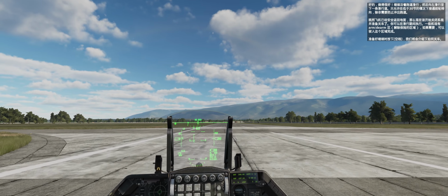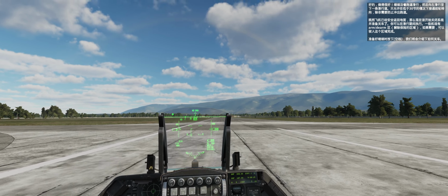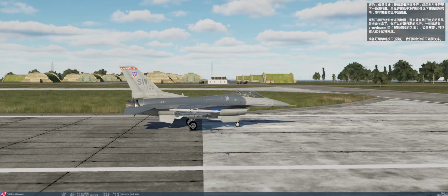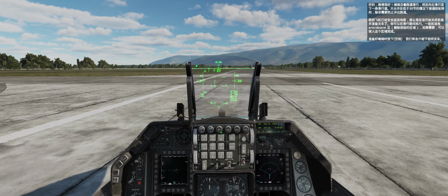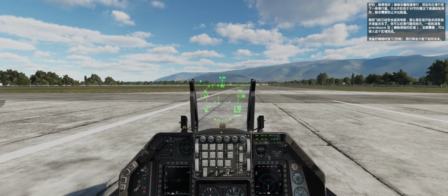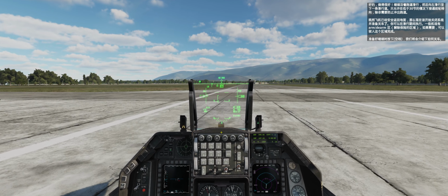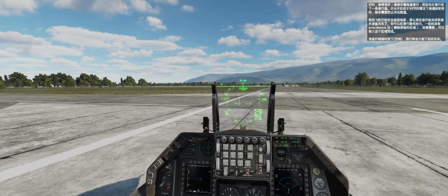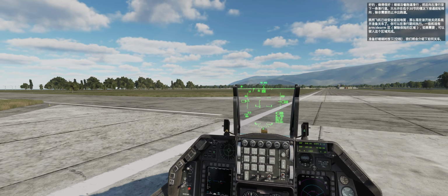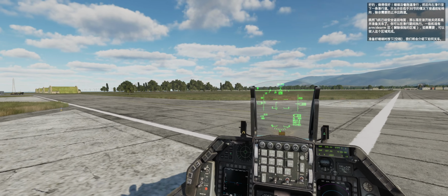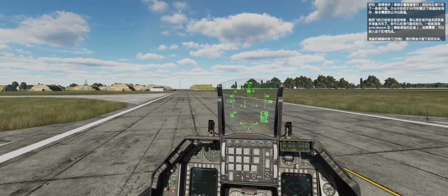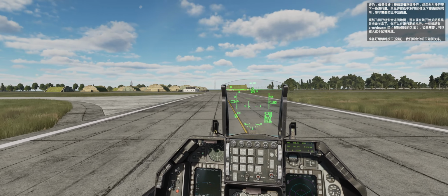Okay, well done. Continue to taxi down the runway and take the next taxiway to the left. Only engage nose wheel steering when below 30 knots, and this is required earlier to prevent departure from the runway. Now that the aircraft is safely back on the ground, it's time to start powering down systems and preparing for shutdown. These tasks may be performed as you taxi. Some airfields also have an arm-de-arm area you can pull into to complete the tasks if desired. Press spacebar when you're ready to continue and we'll have a look at those.